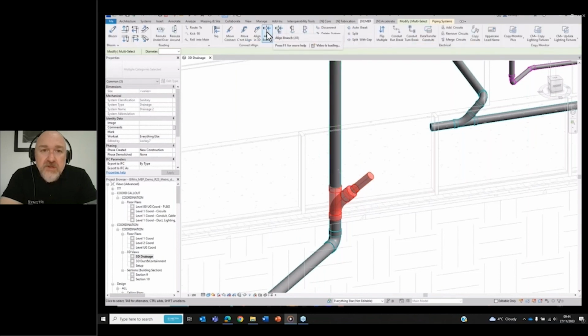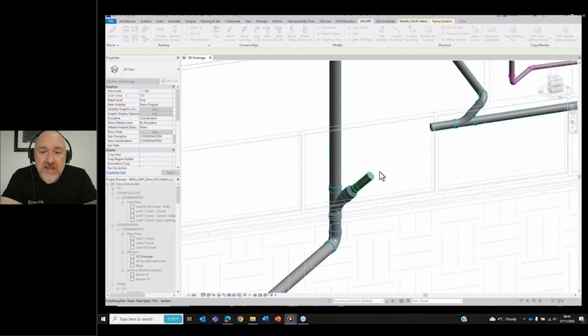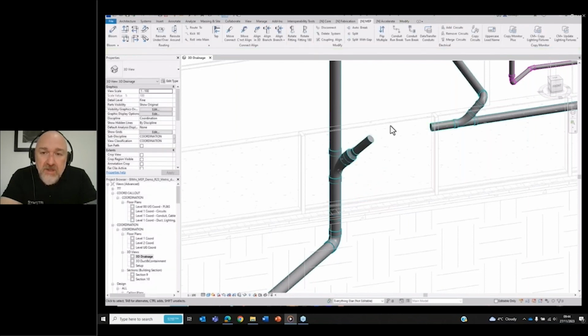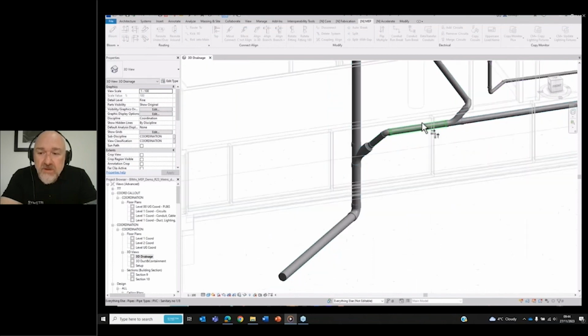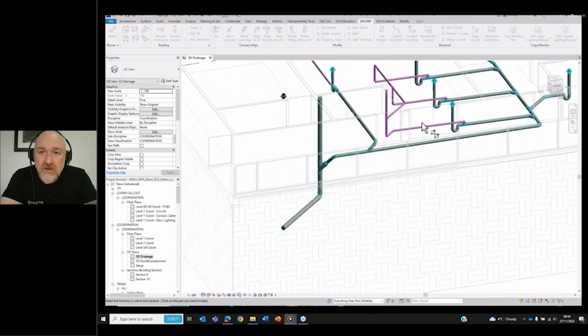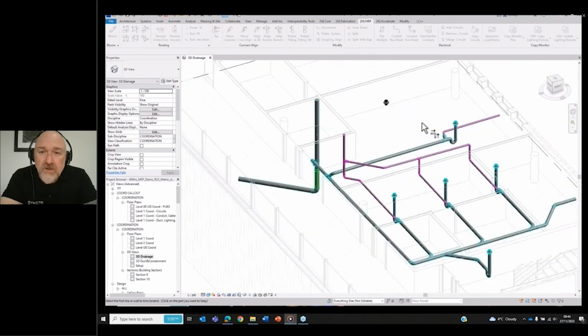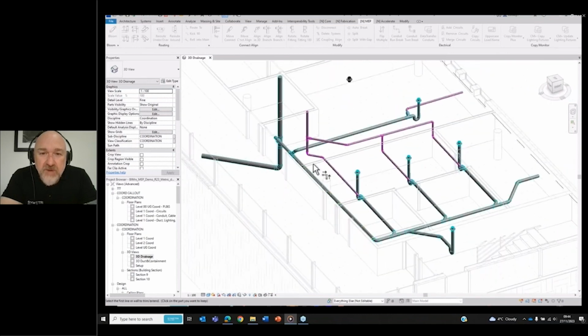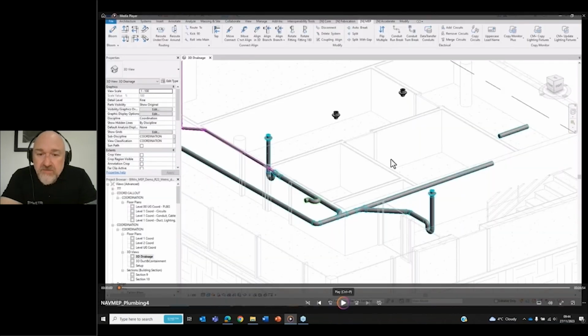Next, we'll just use a line branch. Again, supports pre-selection, so it's going to move the whole lot up. And then we're just going to do a trim extend to corner, and then get that connected in. And there we go. 3 floor drains, some vent pipe in, connection into the stack, and connection into another piece of pipe over to the right there. All under 5 minutes.